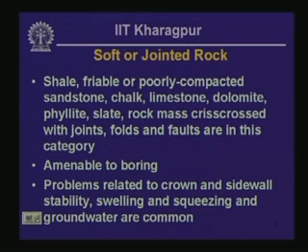Now, if you have got a rock of this type, then the tunnels that are going to be constructed, the tunnel walls in fact are not going to be self supporting. So, more often than not you are going to be set with a problem of designing some measures in order to stabilize the possible failure mechanisms around the walls of the tunnel.